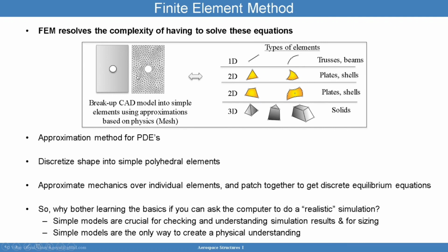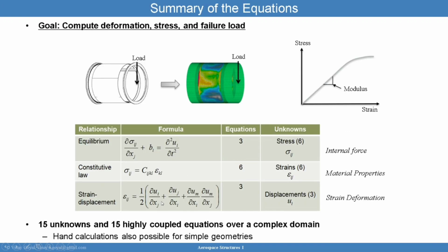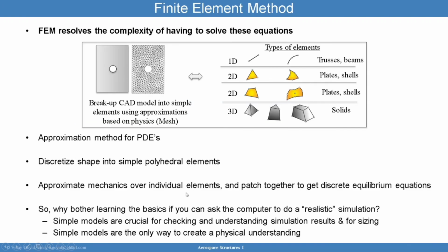And the idea here is to take every one of these triangles, which could have different shapes, and map them into a master triangular element, which is going to be the same shape for every element. So I'm going to try to solve the partial differential equation, these highly complex equations, for the master element. I'll map each of these triangles into the master element, and then connect these elements together.